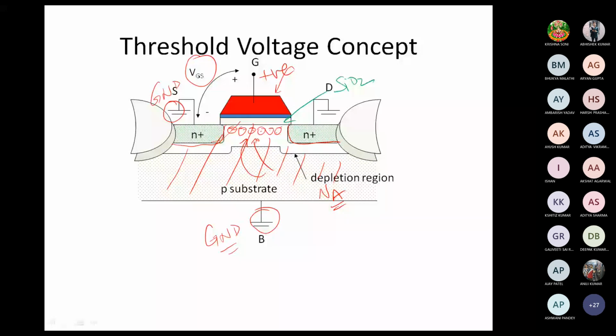So this interface line is the silicon dioxide silicon interface. Initially, as we increase the gate voltage, these electrons are just accepted by these acceptor atoms. They become ionized and have negative charges now. So equivalent charge is induced on the other side.